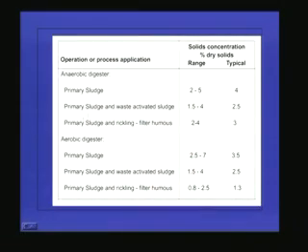And this is the anaerobic digester. For primary sludge, we take the solid concentration as 2 to 5, and for waste activated sludge 1.5 to 4, because this solid concentration is essential, especially when we go for stabilization unit design. These tables are available in design manuals. So we can get a rough idea about the solid concentration usually present in the sludge we get from different treatment units. And as I have already told, this is essential when we go for the design.